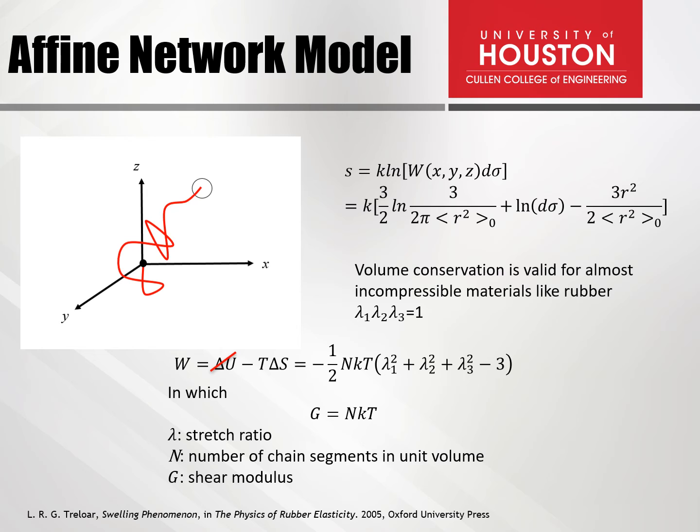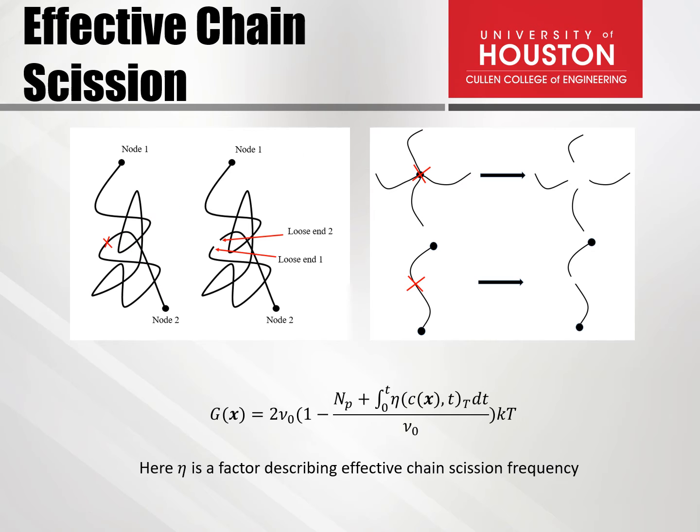Mechanical performance of elastomer is most related to the number of interconnected chains in unit volume here. To get closer to the real case in cross-linked polymers, Flory has developed a loose end correction to describe the influence from chains not connected to the network.